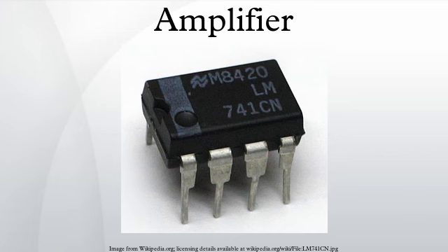The Doherty amplifier remains in use in very high-power AM transmitters, but for lower-power AM transmitters, vacuum tube amplifiers in general were eclipsed in the 1980s by arrays of solid-state amplifiers, which could be switched on and off with much finer granularity in response to the requirements of the input audio. However, interest in the Doherty configuration has been revived by cellular telephone and wireless Internet applications, where the sum of several constant envelope users creates an aggregate AM result.